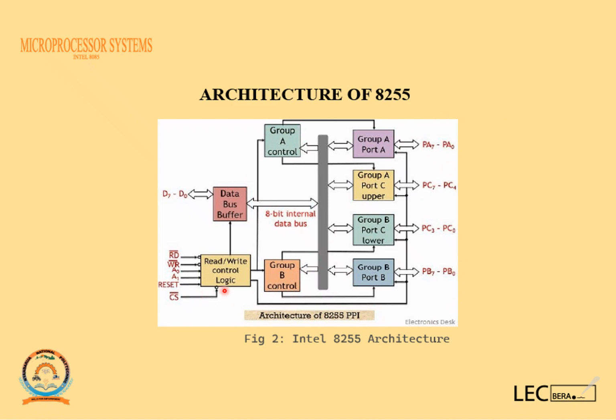And then we have the chip select. Chip select is to enable this IC to be active or inactive. If we want to activate this IC, then we have to drive this pin low. And I think I have to talk about this. You remember I told you that when you see a signal with a dash above it, it means that signal will always be activated if you drive that pin low. When you drive this pin low, then you activate that pin.